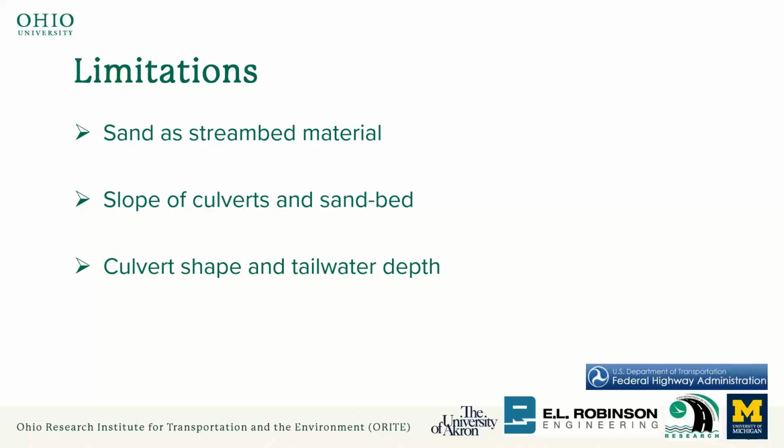So, limitations. We decided to go with medium sand. The reason is that if we use anything finer than medium sand, we might not be able to see what's happening. The water will become like coffee, right? Also, if we use something like clay, it will be more cohesive, which is not what we want. We want to create somewhat of a worst-case scenario.